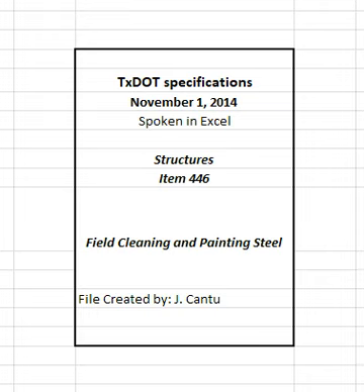Do not place rigging, scaffolds, etc., in contact with previously painted surfaces until the previously applied coating has fully cured. Protect previously painted and cured surfaces with an approved padding to minimize damage when rigging, scaffolds, etc., will be placed on or hung from those surfaces. Avoid and minimize coating damage to the extent possible. Repair all coating damaged as a result of rigging or scaffolding as directed.